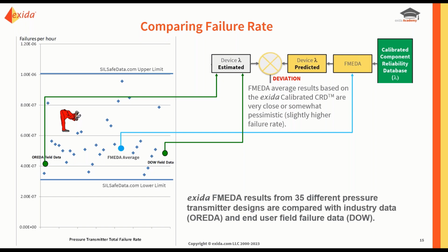FMEDA average results based on our calibrated CRD are very close or somewhat pessimistic, a slightly higher failure rate compared to the field failure data. So when it comes to safety, it's better to err on the side of caution and be a bit more pessimistic.